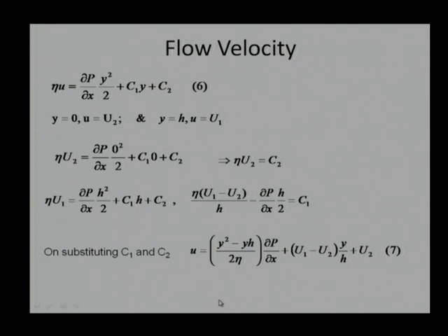So, we will be getting some pressure profile, velocity profile. And another thing is that we have two velocity terms. If we say u2 is 0, then only there will be one velocity term and one pressure term, or whatever assumption or hypothesis was there. Because of inclination there is a boosting of the flow at the exit and a retardation at entrance. So, the same thing is coming from mathematical treatment.